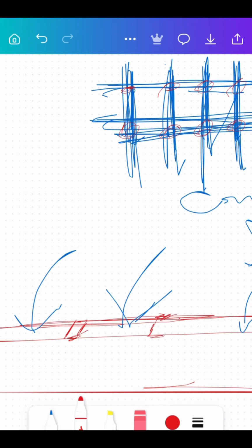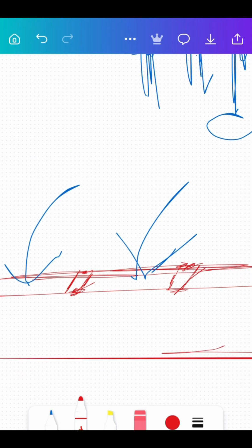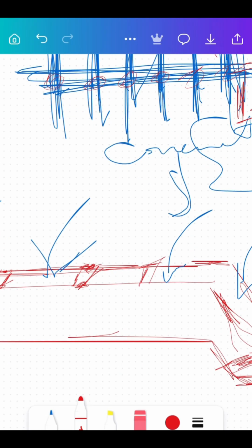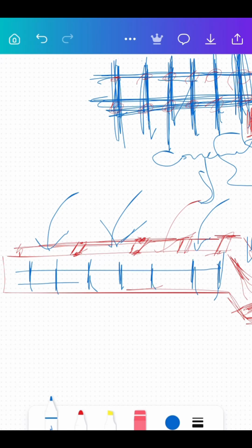So another piece of wood will go here, they are going to nail the wood here, and they'll nail it here and here, so they can hold the boards at the top together. Okay, so they don't spread open. So it's going to brace it, and on and on. So when it's done, we're going to pour the concrete. Remember, it has iron in it, right? This iron that we have here is actually inside. The formwork is done around the iron because the iron needs to be inside the concrete.